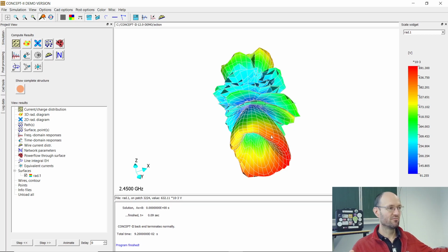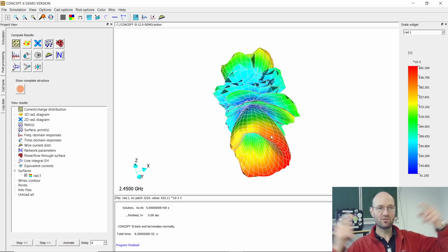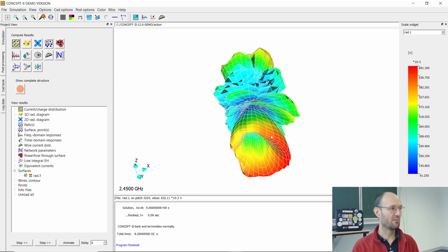The wave will hit the wall, will be reflected, and reflected again, and at some time it will be picked up by the receiving antenna, and you can measure the emission not in terms of maximum field strength at a certain distance, but total radiated power, which is a much more robust measurement for this emission.